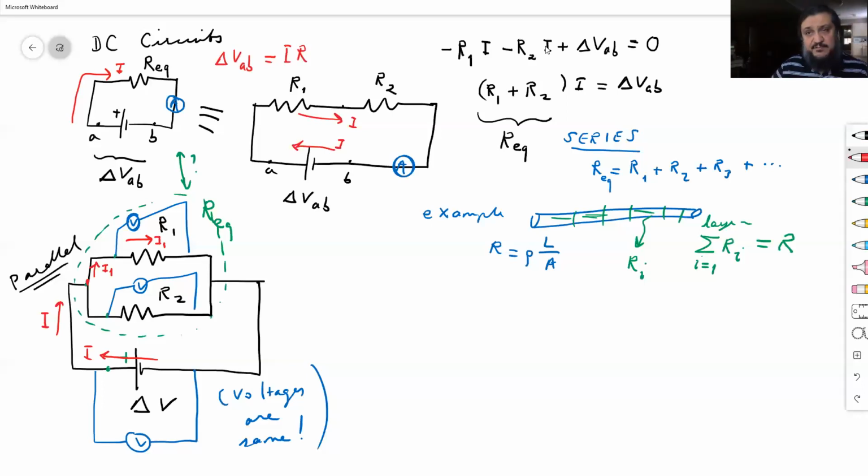Okay? So if you take I1 out of I, what is left? I minus I1, right? So the current that goes through the second resistor is whatever is left from the original current, which is I minus I1. If you will, call it I2. Doesn't matter. It's a different current. I2. So that current goes through R2 and then follows the wire and then comes here. And the I1 meets I2 over here.